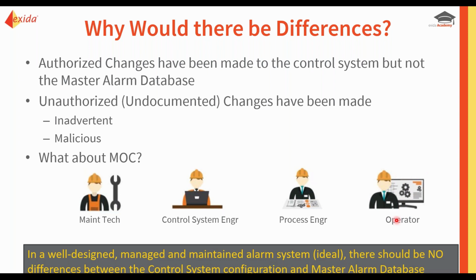So whatever access and controllability is provided to them through the HMI gives them the ability. For example, operators can be set up so that, by virtue of the security and access within the HMI, they cannot change alarm limits. So going forward, if you've done rationalization and put in place a thorough MOC process, combining that with setting the appropriate access controls for each role can help minimize the potential for these unauthorized changes.